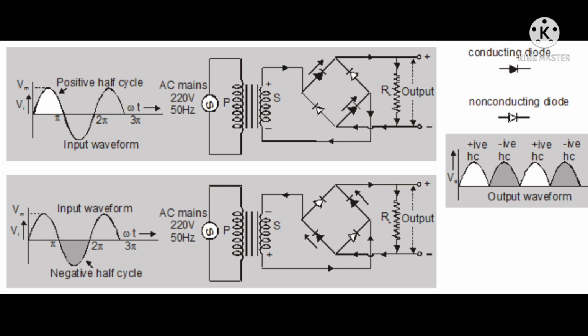These illustrations show a rectifier, an electrical device composed of one or more diodes that converts AC alternating current to DC direct current. A diode is a one-way valve that allows electrical current to flow in one direction. This rectifier diode conducts only when it is forward biased with positive voltage. The current flows through the resistive load in one direction as pulsating voltage.